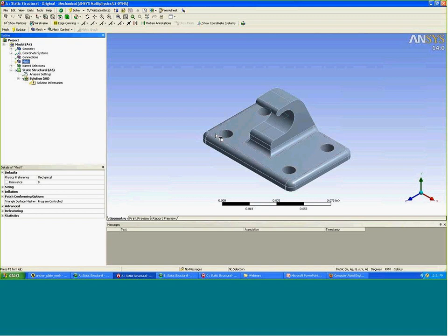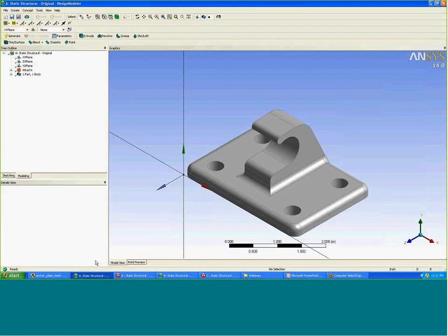And often this is important, particularly if you have complicated CAD parts where you're slicing and dicing and you may have small features that you miss. Ultimately, it's more important that workbench meshing thinks it's sweepable rather than you, and it can help you diagnose where you have difficult geometry. So in Design Modeler, what I'd like to do is show everybody how I would go about creating a brick mesh with this part.